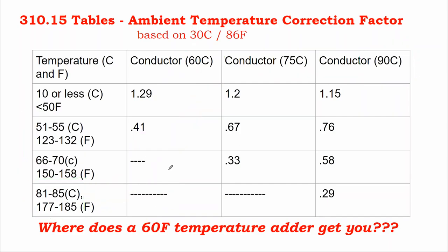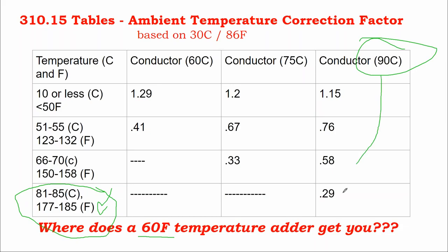Otherwise it'll start burning up. Remember, those cables already generate their own heat from the electricity inside them. So by the time you get into extreme rooftop temperatures where your cables are 1 inch from the rooftop, you have to be using 90C rated cable just to have something that can be safe up on the rooftop.